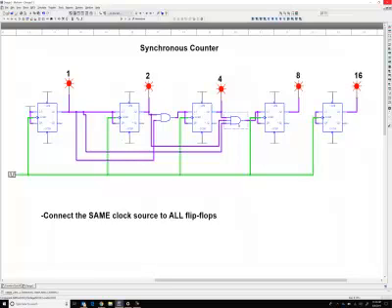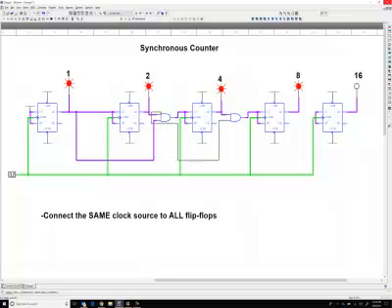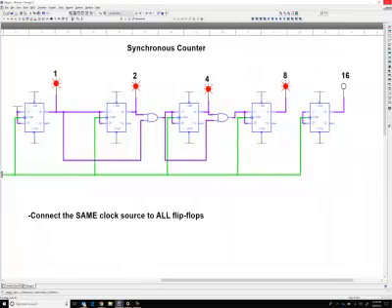But to get around it, instead of doing that, we're not going to use the triple AND gate. What we're going to do, and copy and paste this one, I'm just going to use a 2-input AND gate. And we're going to take advantage of the fact that this AND gate already checked the first 2 bits. So we check the fours place, and we piggyback from this one, because this one already checked the ones and the twos. So this one is a result of the first 2 bits being on and the third one. And we do the same thing for the 16th place.